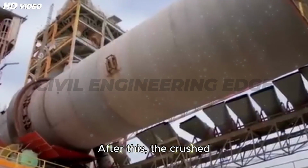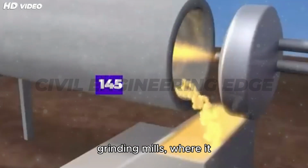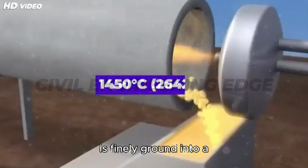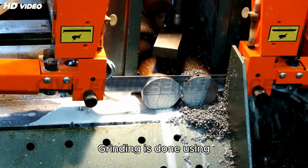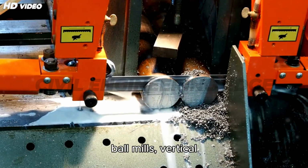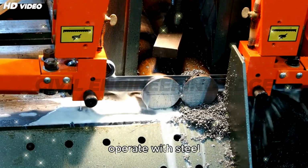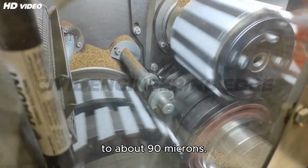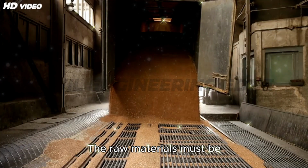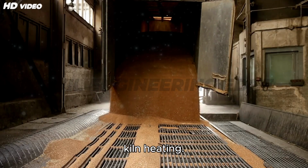After this, the crushed material is transported to secondary crushers or grinding mills, where it is finely ground into a uniform powder, known as raw meal. Grinding is done using ball mills, vertical roller mills, or hammer mills, which operate with steel balls or rollers to reduce particle size to about 90 microns. The raw materials must be finely ground for proper chemical reactions during kiln heating.